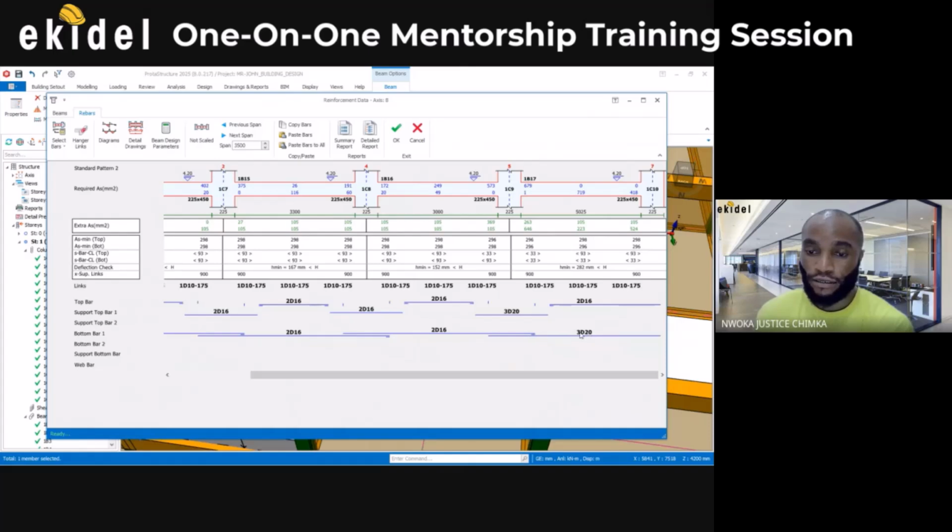You can see that, although based on the span, I can choose to control this now using steel. I can still use D16. Let me see if I do that. So decrease this now to 16. It is unfailing here. Then increase to 4 numbers. I can see that it is passing.